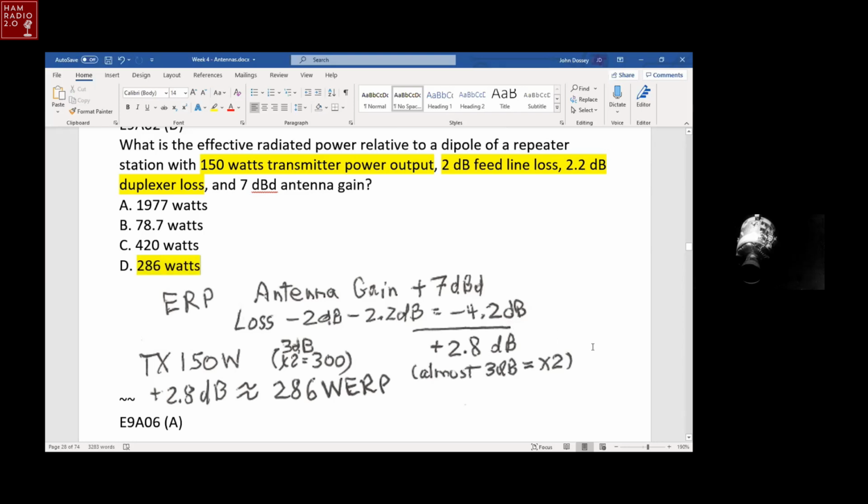Okay, rewind on that one. That's the usefulness of rewind. You'll have to watch the movie to hit rewind. No, I got the up to the approximately 3 dB. Right. Okay. So approximately 3 dB. If it was a 3 dB gain, that's doubling the power of the transmitter. So that would be 300 watts. But it's not quite 3 dB. That's what I missed. Doubling. Okay. 300.